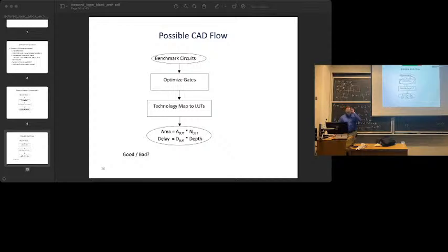So you basically turn all of that into logic equations and you start simplifying them using a bunch of algorithms that are kind of like the Karnaugh maps you learned in second year, but applied on things with maybe millions of variables automatically. So you try to reduce the gates, you get rid of unnecessary ANDs, etc. Now we don't really have gates on an FPGA, so then you have a step called technology mapping.